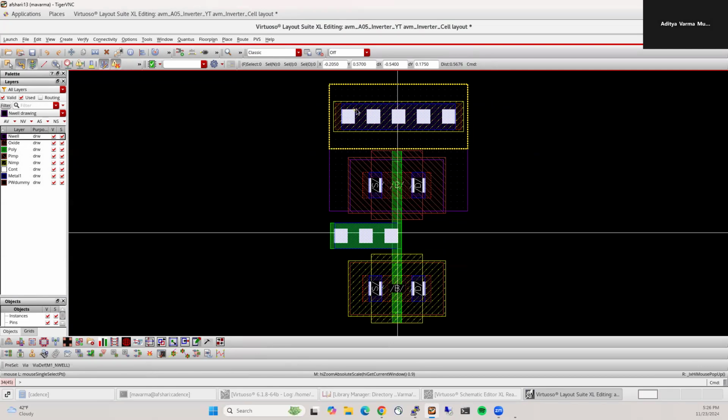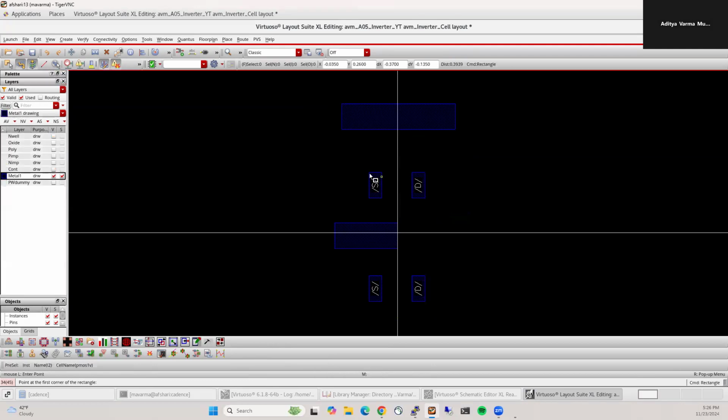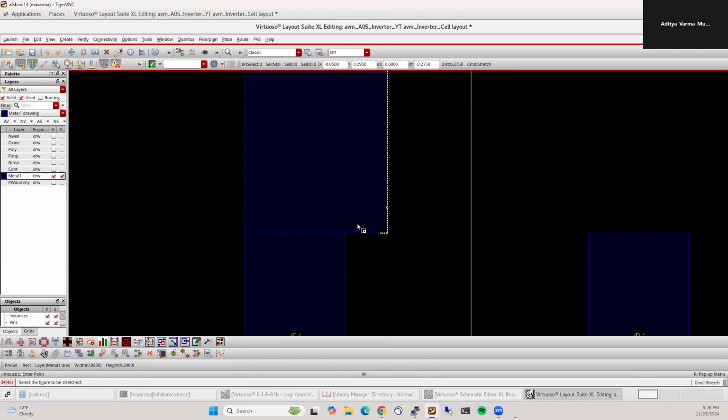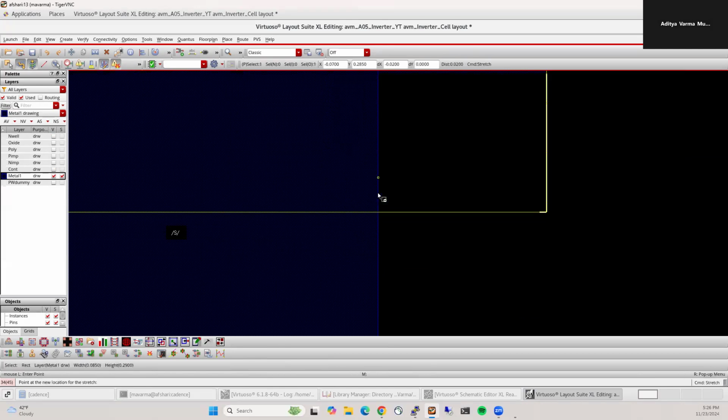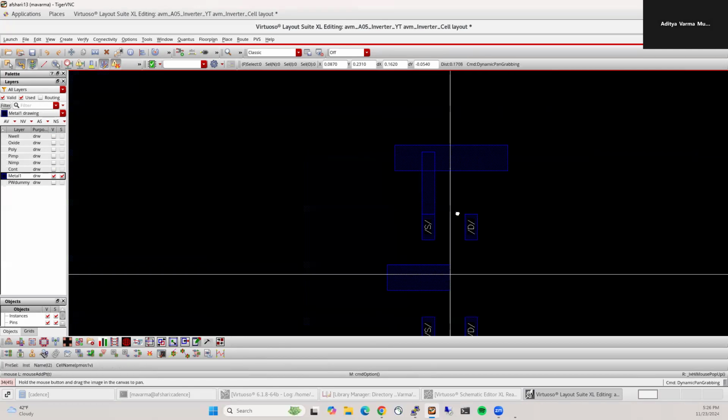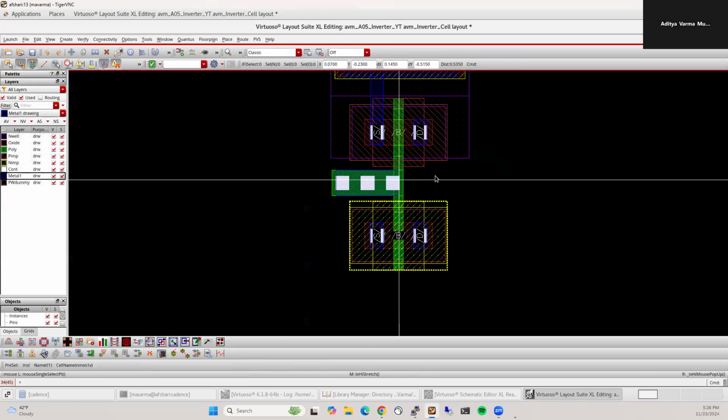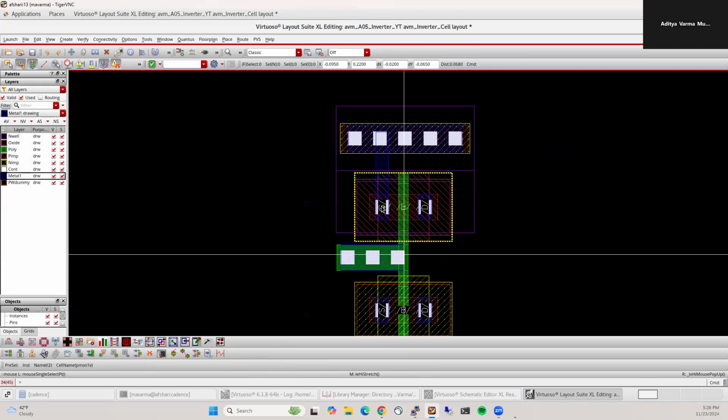And this needs to go to VDD, right? And also the drain connects to VDD as well. The source connects to VDD as well, right? It's PMOS. So I'll click M1 and then create a rectangle. Create it like that, and then bring this in. There we go. All right, and then that essentially connects the source and the body to VDD.